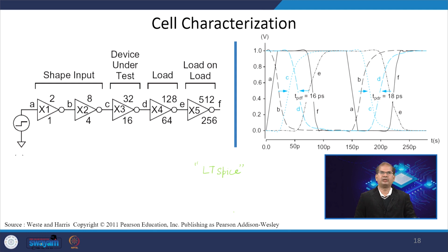This is related to the combinational circuits. In this lecture, we discussed the timing library .lib file, what is inside that timing library, and how we can generate the delay tables inside the timing library using SPICE simulation.